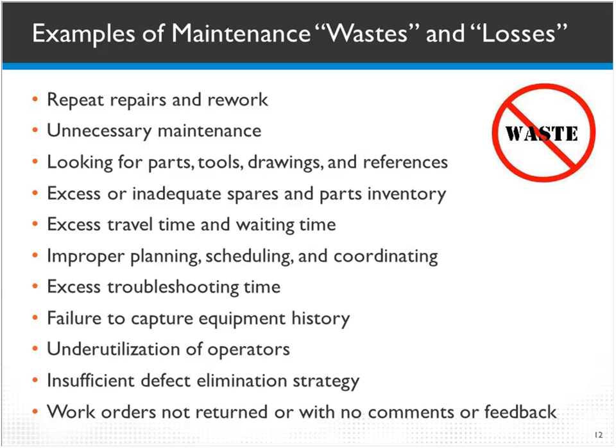It's an opportunity analysis. We go look around at so many different maintenance groups, and we see some of the things that impact their wrench time being low, because wrench time in some cases is less than 20%. But what we see is a lot of repetitive repairs that have been going on, and there are a number of root causes why. And there's a fair amount of rework, whether a contractor does a job and then we have to redo that job the next day or the next week, or we rebuilt this pump and, gee, it's already failing two weeks later.